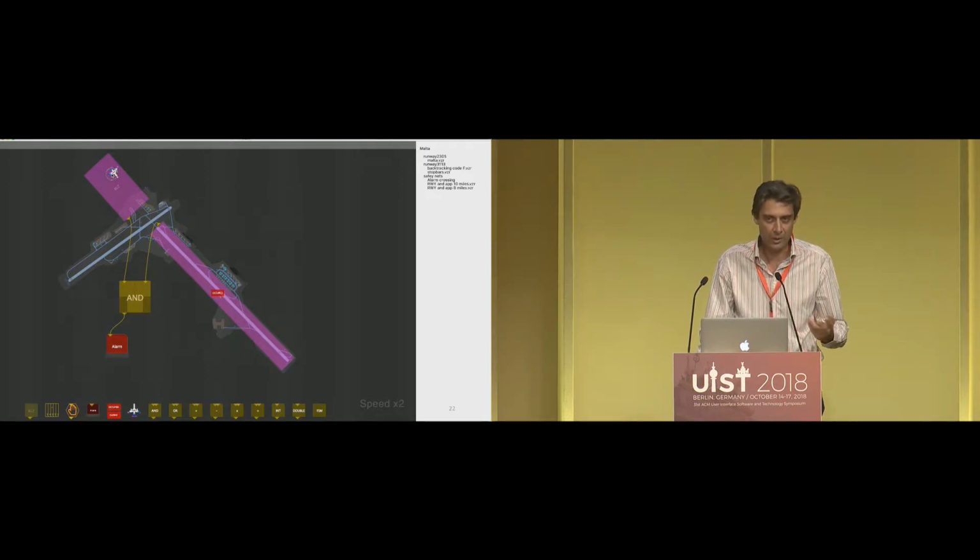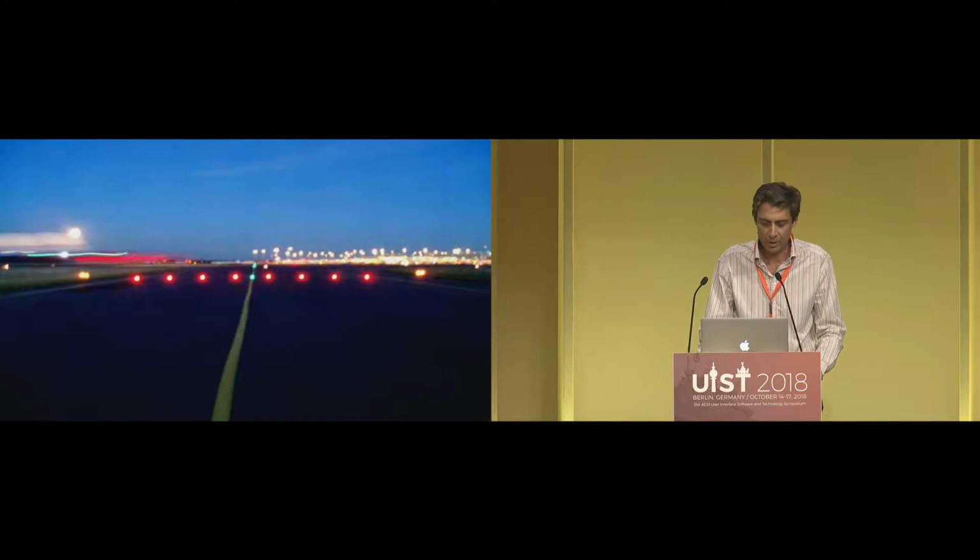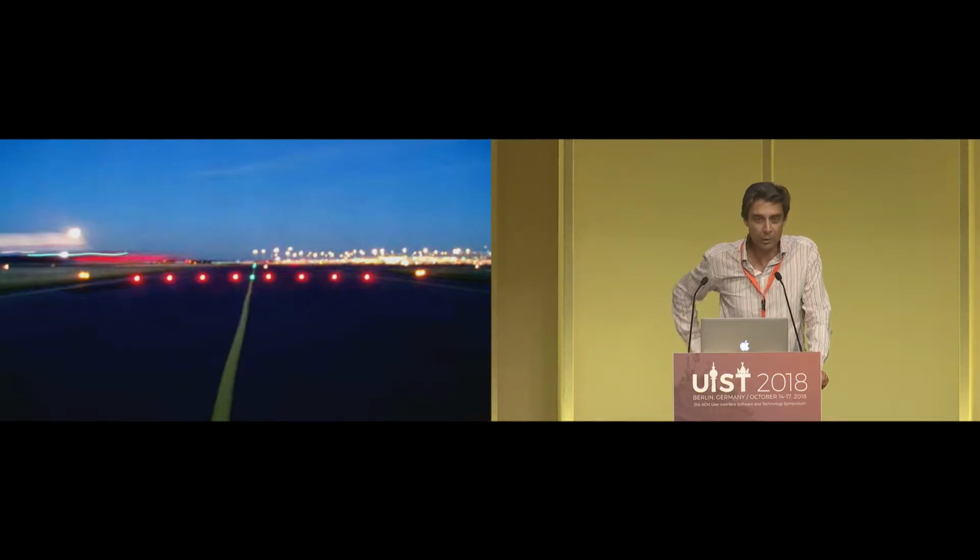So we've seen two examples with alarms. Now let's see another example, related to what we call stop bars. Stop bars are unidirectional lights that provide protection at runway and taxiway intersections and reduce the risk of runway incursions. Pilots and vehicle operators are required to stop at the runway hold point and wait for the controller to switch off the stop bar.